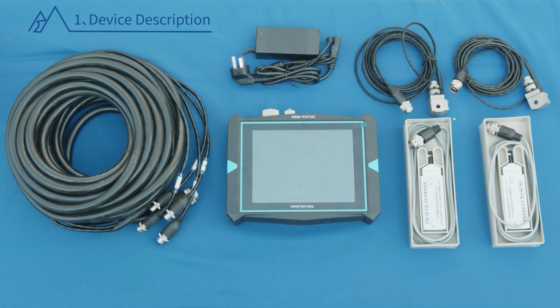2. Applications. The instrument is suitable for testing the vertical compressive bearing capacity and pile integrity. Monitoring the pile body stress and hammering energy transfer ratio during driving of precast piles provides a basis for selecting pile driving parameters and pile length.